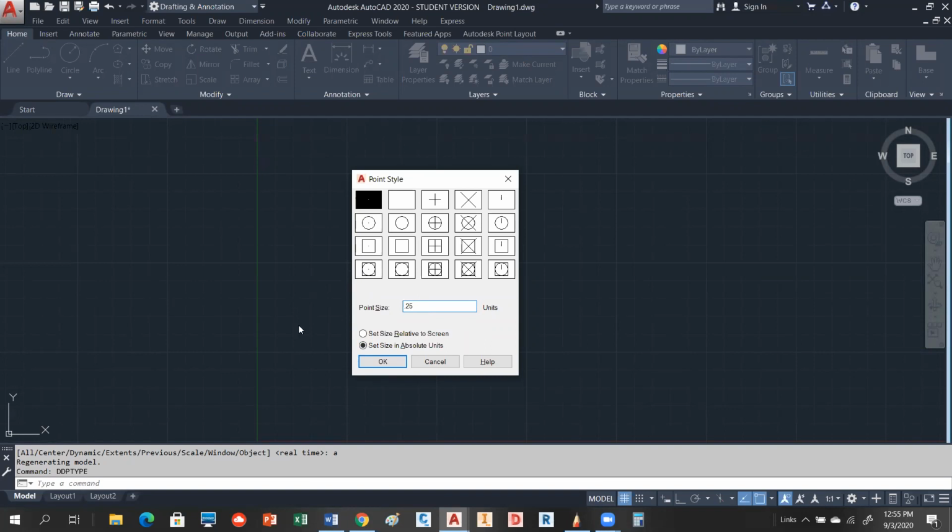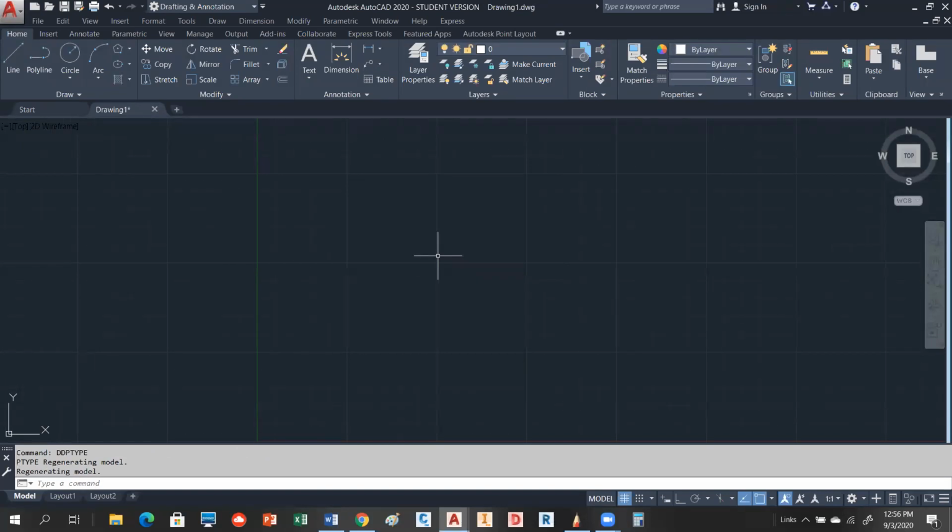And let's choose this PD mode right here, which is actually 0, 1, 2, okay? So we're going to go to point style 2, PD mode, PD size of 0.25, and go ahead and hit OK. Why that is so important is that when you set that up, points are going to be governed by those settings. Whatever those current settings are, that's how it's going to work, okay?